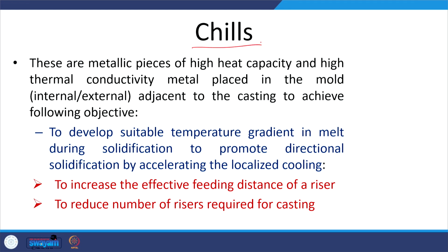Now, the chills, as I have said, are metallic pieces of high heat capacity and high thermal conductivity. These are placed in the mold suitably. These can be placed within the mold or outside the mold adjacent to the mold surface. So, placed internally or externally adjacent to the casting mold surface or within the mold.